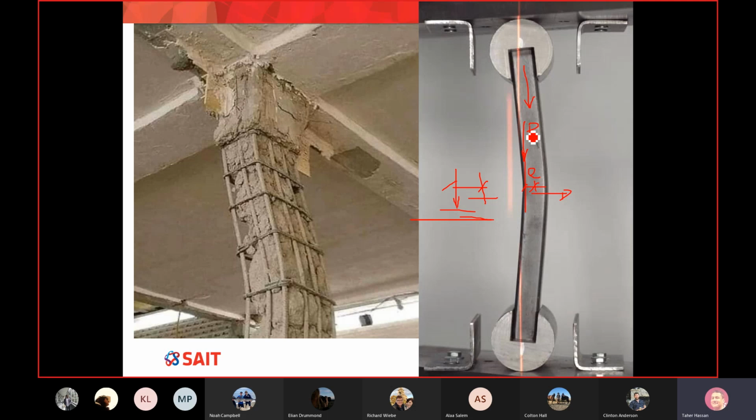We will get eccentricity, and it's a kind of chain reaction because when we add load, the load will generate buckling. The buckling will generate bending moment. The bending moment will deform your member more, and this will simply end the life of this member. So simply the element will fail, and that's why buckling will cause a failure for your member.